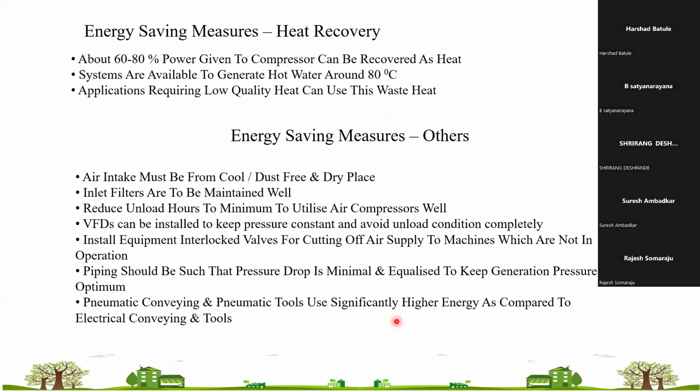That's how your compressor will always be in load cycle, but at various speeds. The energy consumption of the VSD compressor will be less than 6.5 kilowatt to deliver the 200 CFM to your plant.